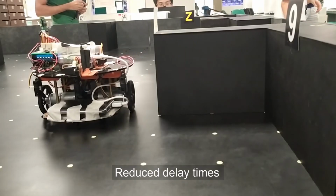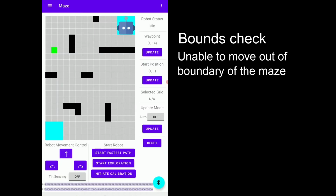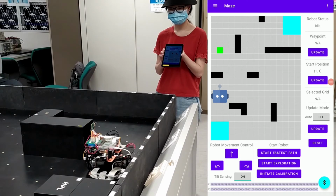We also used multiprocessing instead of multi-threading, and it made our robot much faster. We set the UUID of the Android to connect well with the RPi. We prevented the robot from escaping by implementing condition tracks. We also implemented tilt sensing as an alternative way to control the robot.